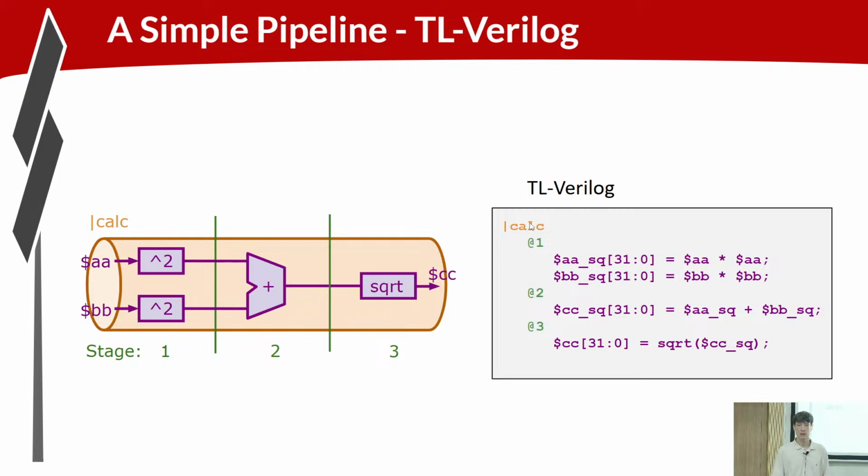You can very directly translate a diagram like this to code. Okay, so this is the syntax in TL-Verilog. By placing your logic in context, you derive from the context the flip-flops. In this representation of the pipeline logic, I'm not expressing the flip-flops explicitly. So that makes my logic not just easier to express, but easier to modify, and we'll see that coming up.